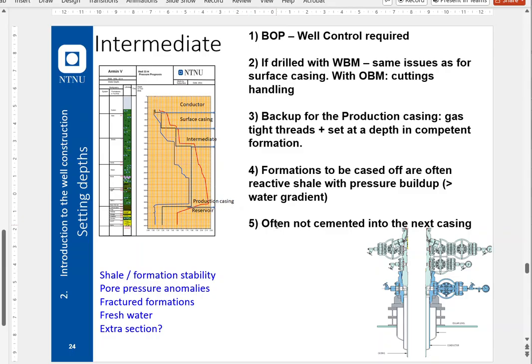What we do, I'm just going to finalize that part. When it comes to cementing, if we look again at the pore pressure prognosis, I would cement as far up so that I have a little bit of leverage when it comes to this pore pressure, so that we have this pressure covered by cement as far as I can. As much pressure as possible. Why? Because a high pressure often means that there could be seeping gas from a shale given enough time. So that's a good practice, not a rule, but a good practice for cementing and supporting the casing.